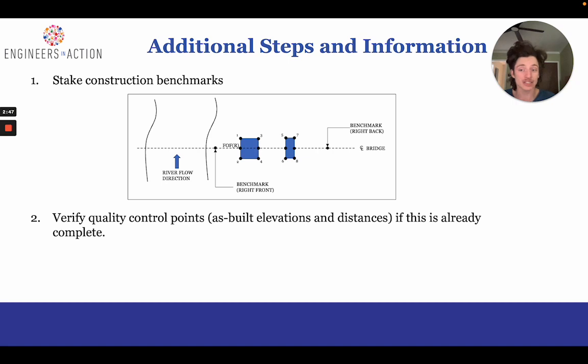We can slightly adjust our abutment length within its tolerance. And this is much easier than having to rerun all the calculations for a different span or a different delta H if we wait until later in the process and we don't realize that our span is off or our delta H is off until we've already constructed the tower. We've already constructed all the tiers up through the tower and all of the other activities that have gone on up to that point.